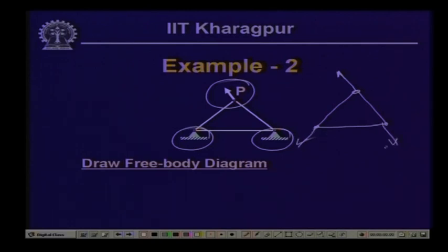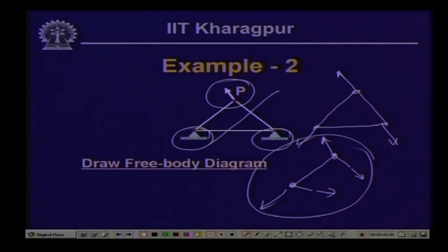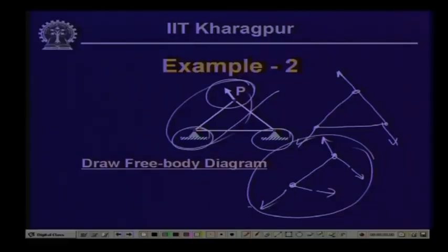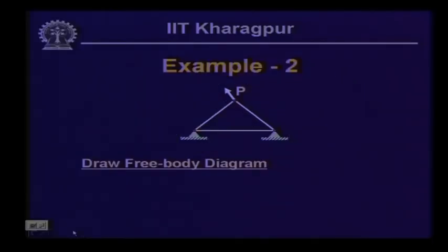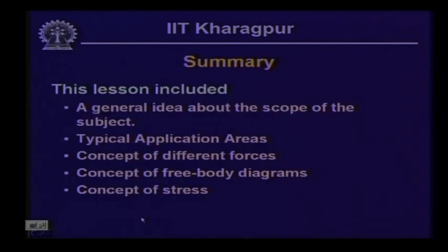They could be in this form, or we can take a cut in this structural form, and thereby we get the reactive forces, the active forces, and the member forces. So, this is the free body diagram of this particular part. This is how we make the structure or the elements free from the supports, or take a cut and draw the forces, which gives us the free body diagram of structures.